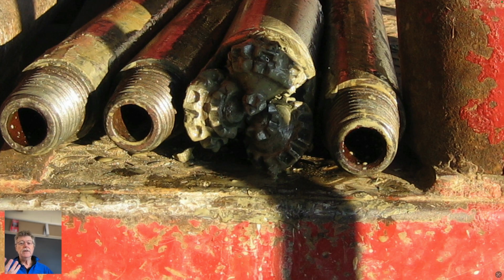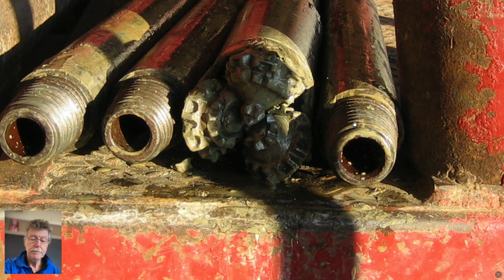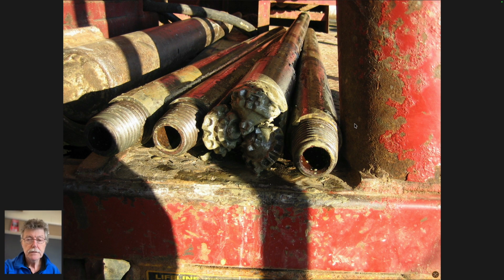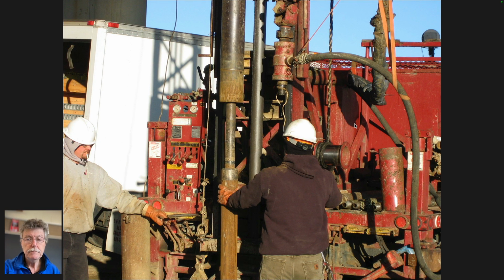And it makes it into a piece of cutting that is then washed by fluid that comes down the middle of this, down the hole from the middle, washes across these, and washes back up this. These are the threads. They're all tapered so they can be put together quickly and undone quickly. The string that we saw would go around this just to be able to seal it. So that's what you see. Again, the string here, drill fluid.